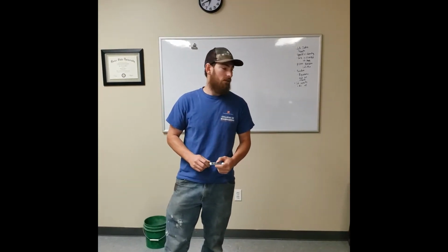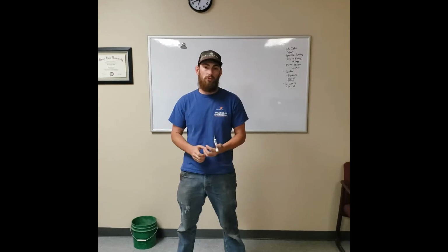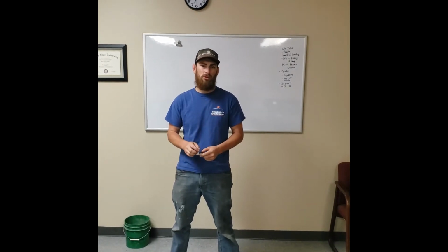So I know it's online, it's not ideal, but I'll try and keep it as short and sweet as I can make it. So for the first lab, as per the course outline, we're going to do specific gravity of soils. Moisture content is also on there, but it's going to be built into the lab, so you're only going to write the one report for the specific gravity of soil solids.